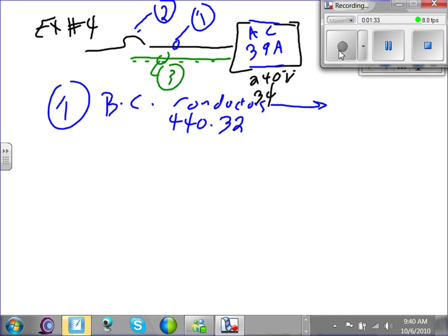It will tell you to size the conductors at 1.25 times the full load current, continuous load. That's what it tells you. It's a continuous load. Okay, so I have a 1.25 multiplied by the AC, guys. They have a nameplate current. You use the nameplate current for ACs because they don't size them in motors, they size them in tons. We use the nameplate current for the unit. So what's the AC full load current for this unit?